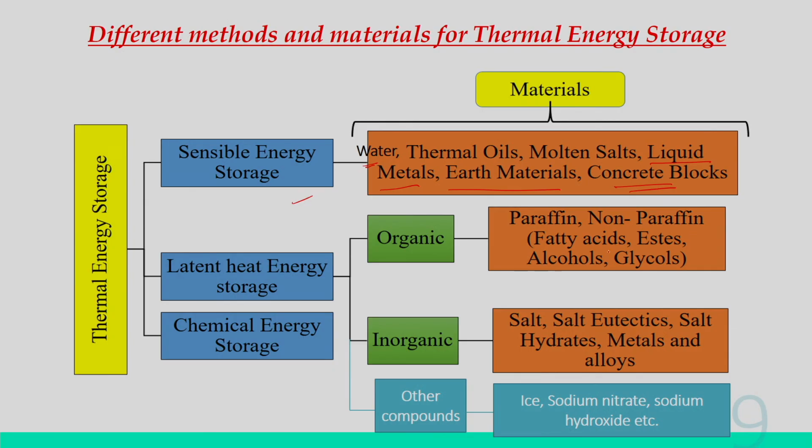Non-paraffin is also there, like fatty acids, esters, alcohols, glycols. And under inorganic, we will have salt, salt eutectics, salt hydrates, then metals and alloys. And for other compounds, we may have ice. So, ice can also be used as an energy storage material. Then sodium nitrate, sodium hydroxide, and many more materials.